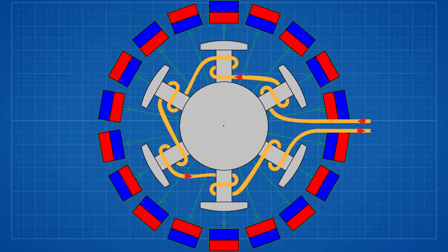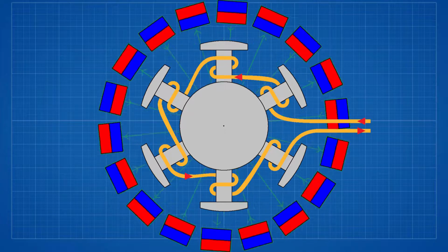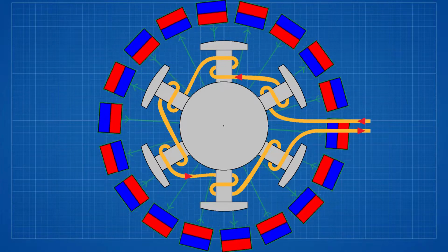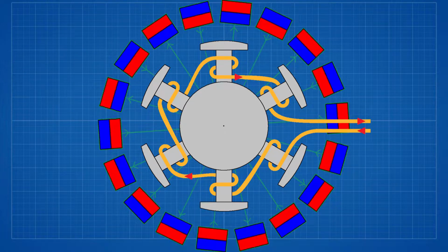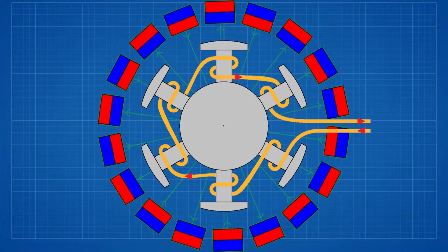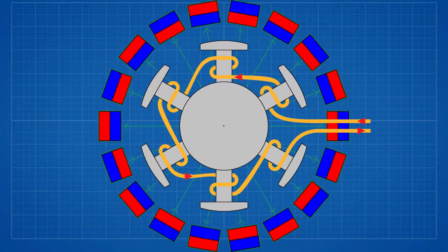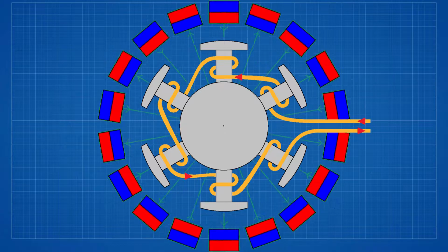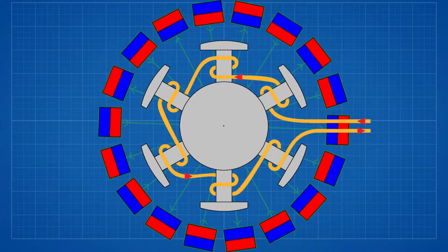Generators consist of two parts: the stationary stator, which holds the copper coils, and the rotating rotor, which holds the magnet. To create a complete circuit, we must take a copper wire, wrap it into multiple coils, and place those coils opposite of each other within a stator. Because of the movement of free electrons, a current will start to flow in the circuit. This means that it produces a current that is constantly changing. This process is called electromagnetic induction.